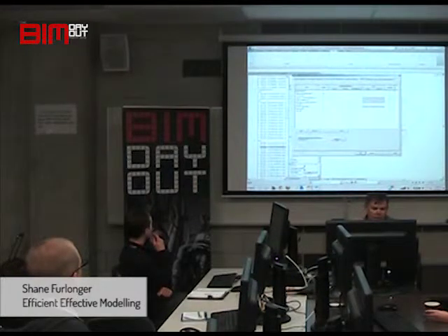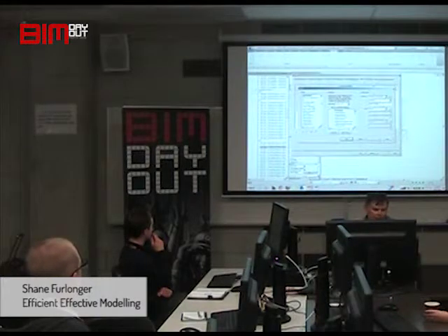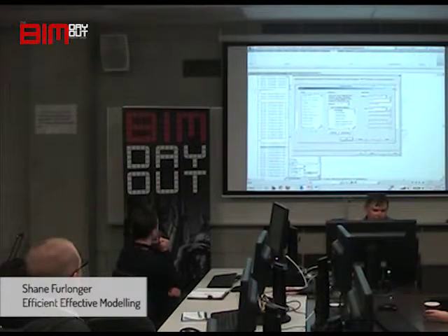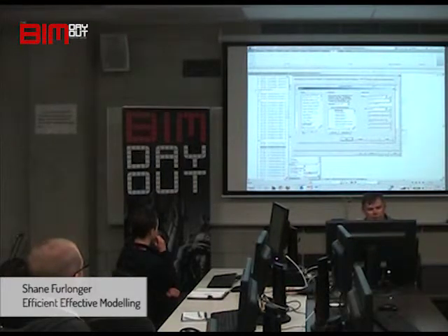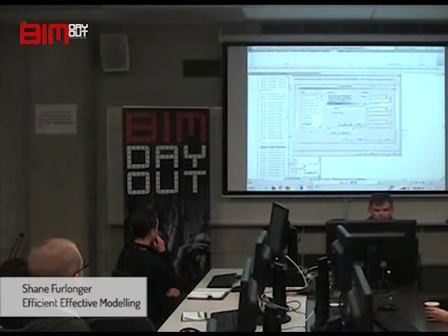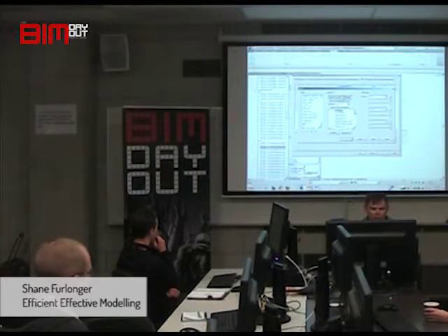When you want to create a new filter, you go here, edit, new, and you'll have your list of what filters you've got, what you want to apply them to and how you want them to be applied. So create a new filter. Let's call it test, and we're going to apply it to, I don't know, walls.